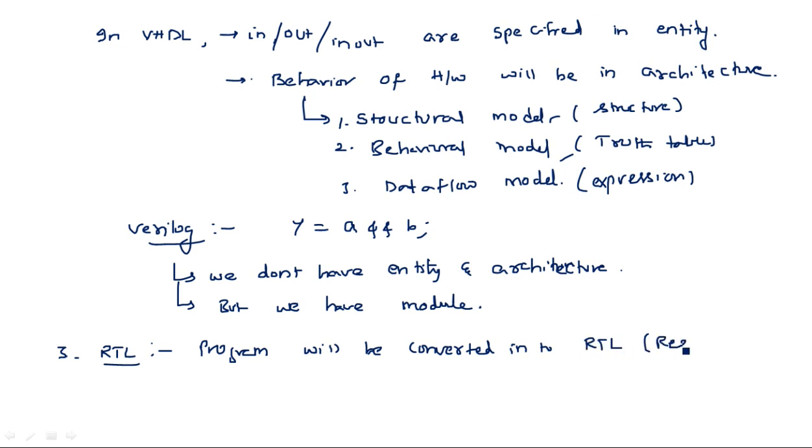RTL stands for register transfer level. So here what happens, the completed program will be simulated, and then we will have the register transfer level. All the description we have written so far will be converted into registers, and lookup tables are created and they are interconnected based on the written program.